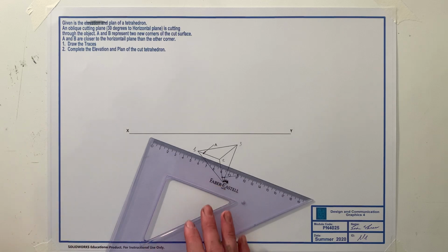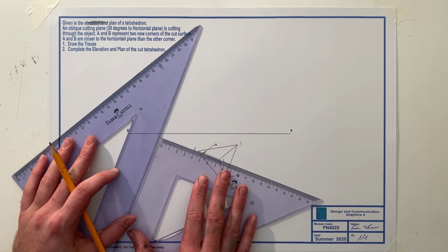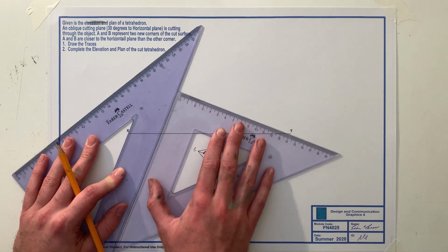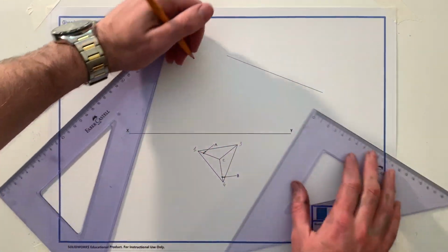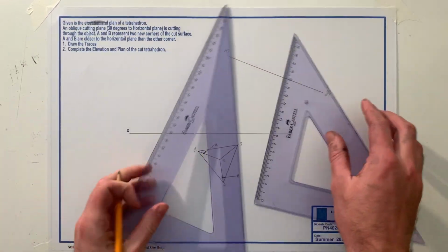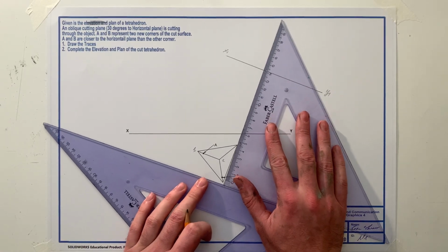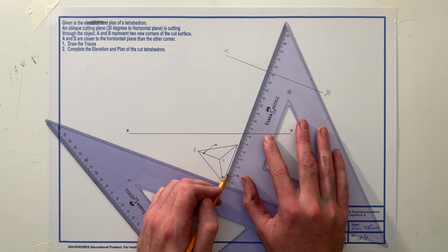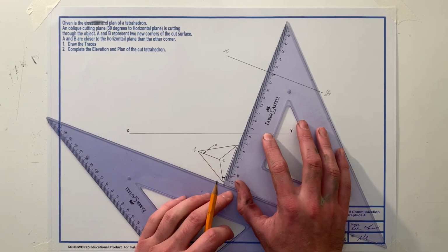Now the one that I think is the handiest to take here is line 1 to 2, just ensuring that I keep it away up out of my drawing itself. So I'm going to carry it way up out here, out of the way. Call this my X1, Y1 line. Now I'm going to take all my lines perpendicular to this line here. I know because of the tetrahedron that my baseline here is going to be perpendicular to its opposing line.